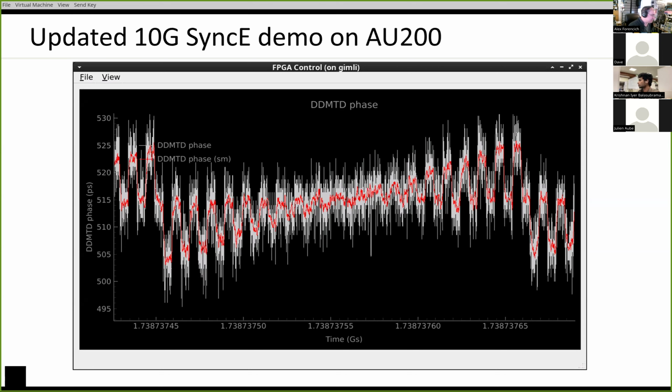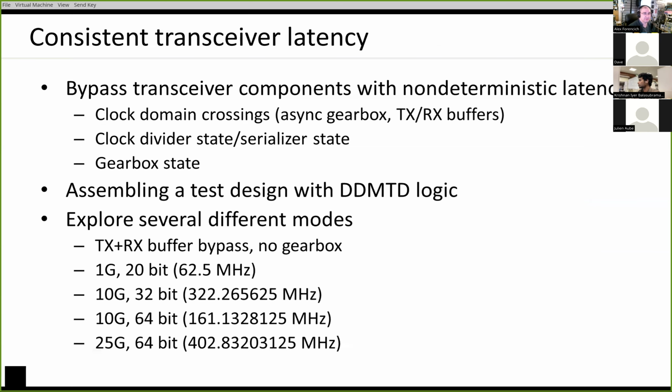This demo was done at 10G with the asynchronous gearbox. The idea is to move the transceivers to a configuration that has a much more consistent latency. Like I said, we're looking at consistent latency, not necessarily low latency, although they tend to come hand in hand.